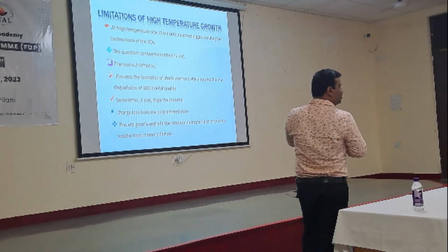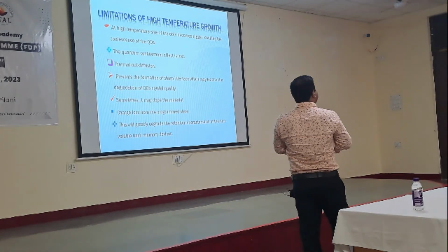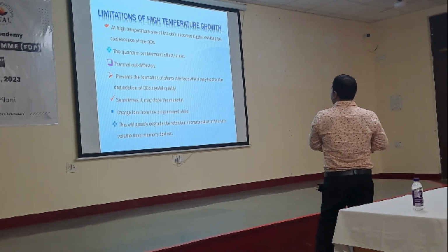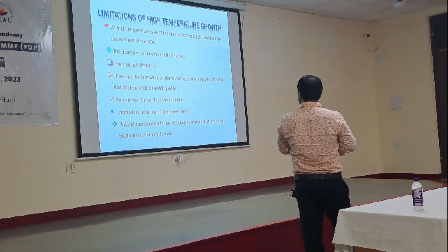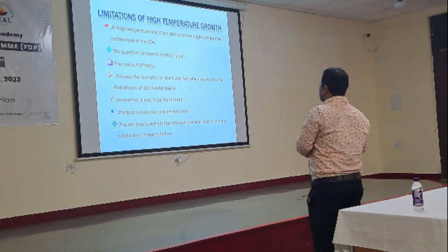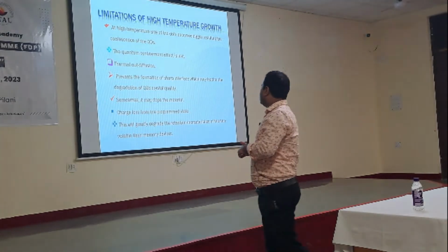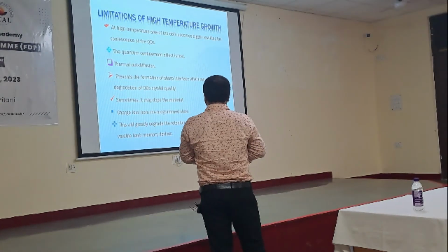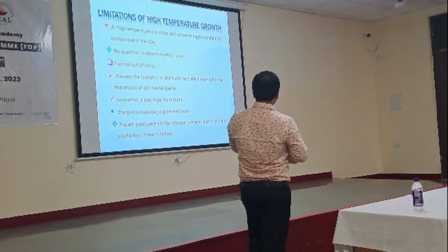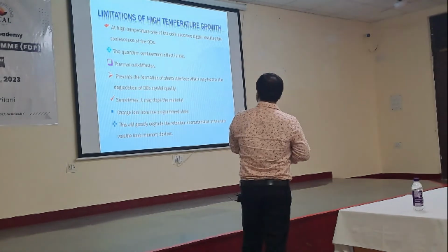Again, thermal diffusion will take place, your crystal quality will get degraded, and sometimes it may dope the material. Eventually charge loss happens from the programmed state, and this will greatly degrade your charge retention characteristics for memory application.